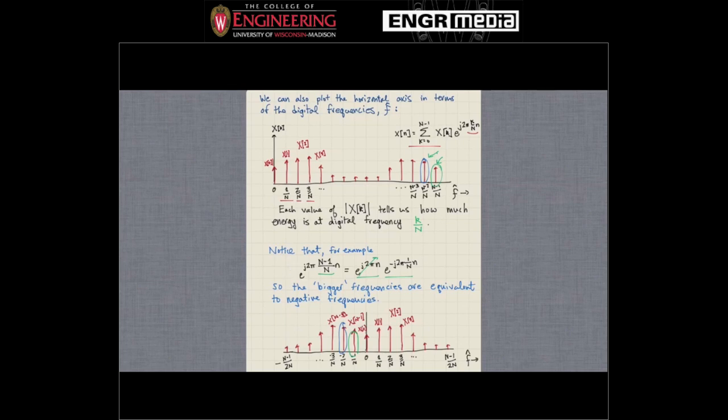We kind of saw this in lab, because when we ask MATLAB to compute the FFT of a signal, it gives it to us in this form up here, where k goes from 1 to n. But then we can use the command fftshift, which we saw in lab, and we get a spectrum like the one written here. So the two things are actually equivalent.